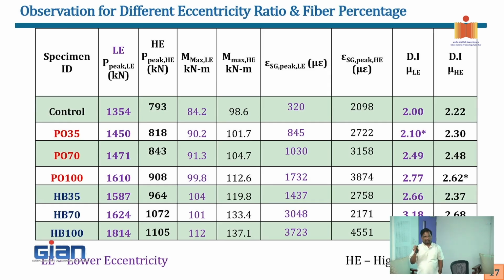Again, about GFRP rebars, people think that, oh, it's very brittle. But it is very elastic. Yield strain is 0.002, but what is the strain at failure for GFRP rebar? We said 2%, right? Even if I bend it up to 2%, and just before that I release it, what will happen? It will go back to its state. The system is very elastic. So it's literally like a rubber band. It doesn't yield, but it keeps stretching. At one point of time, it will snap. But if I release the load before that, everything will go back. So GFRP rebar is a highly deformable system, but it's not ductile.